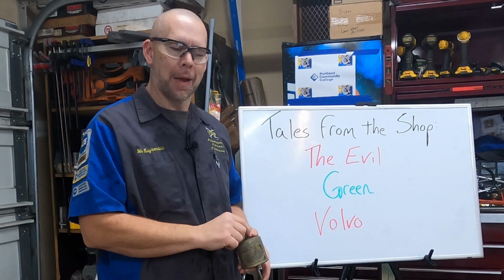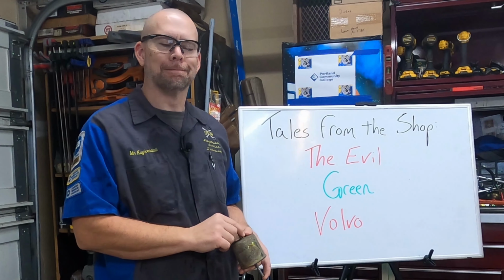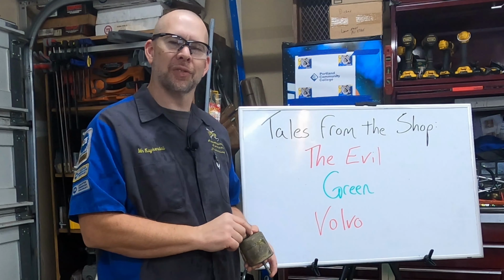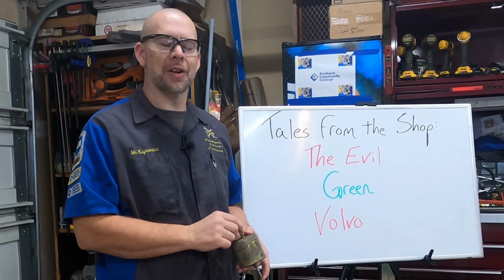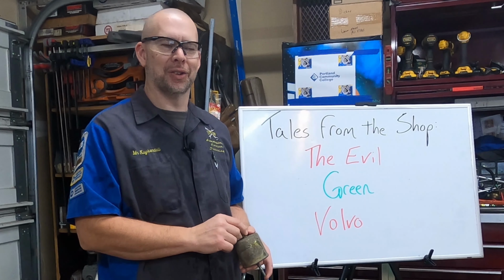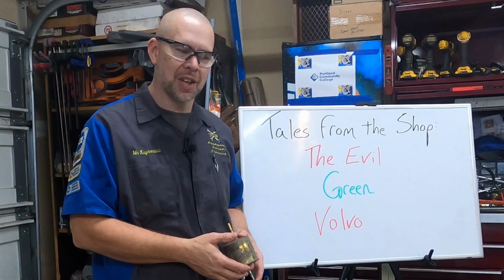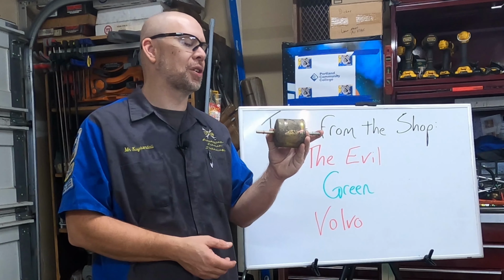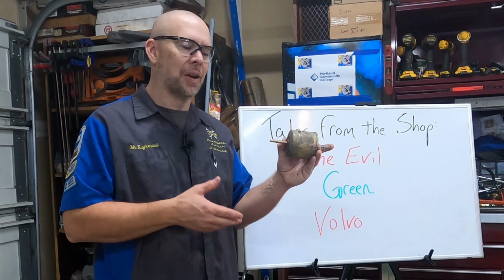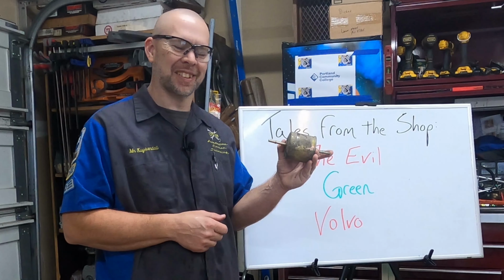So, the fuel filter's plugged up, simply needs to have a fuel filter replacement, and that ended up fixing our Volvo. Had they simply followed the proper procedures, it would have taken care of the car in the first place and it wouldn't have been back on the hook. So that's an excellent place to utilize and trust your tests. In this case, the simple weight of the fuel filter, how heavy it was, actually already told me how restricted it was. My blow-through test was just the icing on the cake.